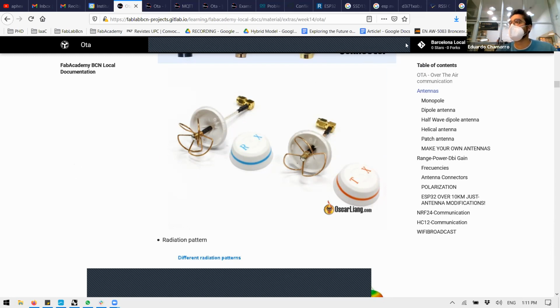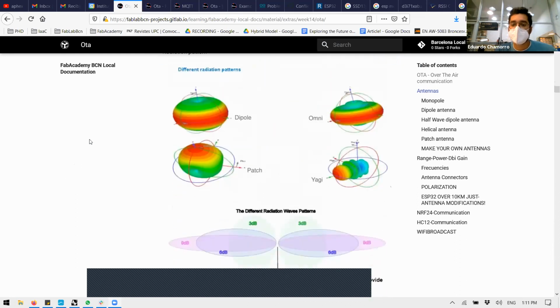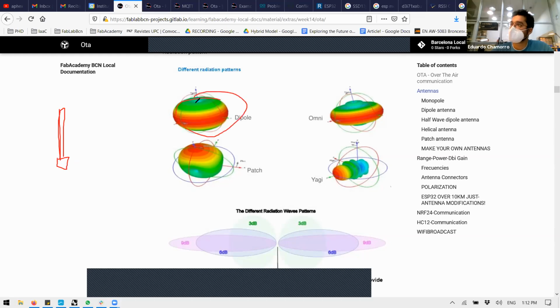And this is about directionality, omnidirectionality. We have this radiation pattern of antennas. For example, the standard plastic antenna that you are familiar with is a monopole, and it has a donut shape. So actually the antenna is not sensitive at the top. There is a real mismatch. A lot of people think, hey, I don't get coverage, I will get closer to the antenna because it's where it's pointing. Actually, this is the worst location you can be. It's way better to be exactly on the straight side, the perpendicular side.